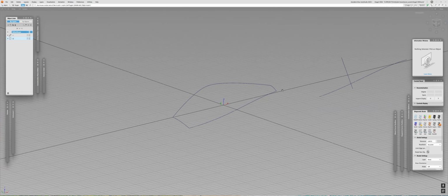Now, as you can see, I've left only the boundary representation of the piece I need to model. The reason for that is, in general, when you start fresh, which means you don't have any scan data, you don't have any reference mesh, nothing, just a sketch, the cross sections in the sketch are actually quite painful to do because they are rarely realistic enough to use as a guide in 3D, especially when we're talking NURBS modeling. The boundary, though, is quite easy to do, specifically in a sketch.